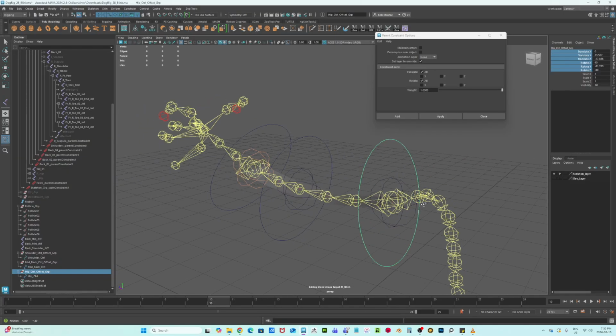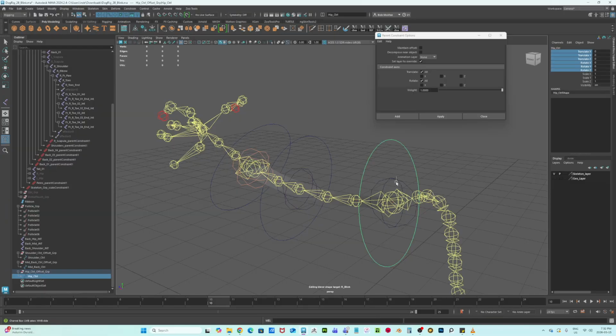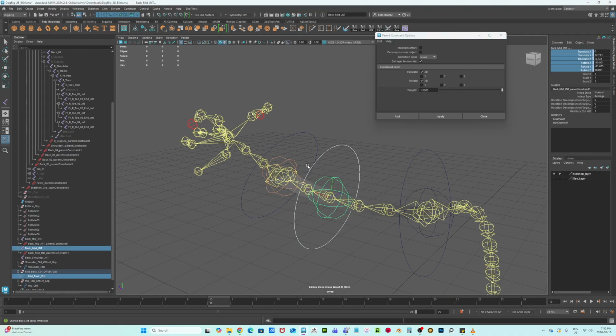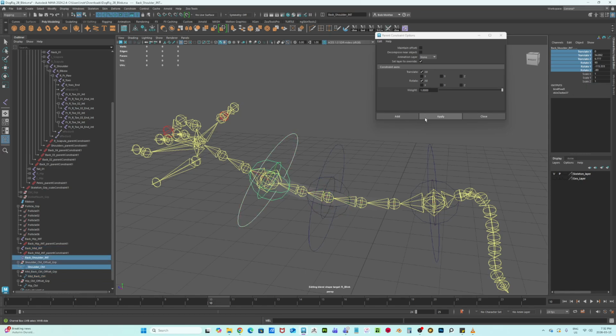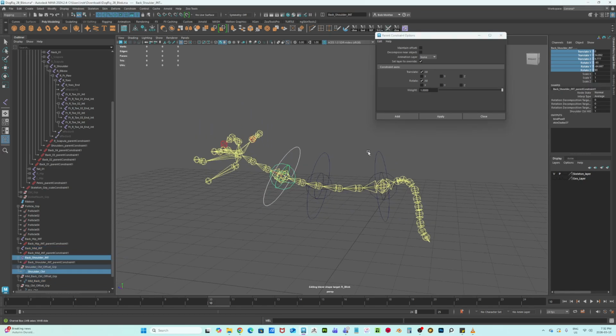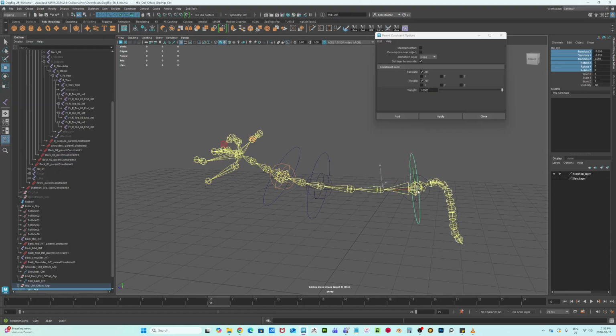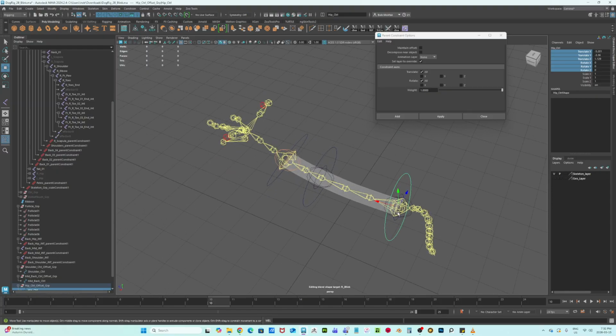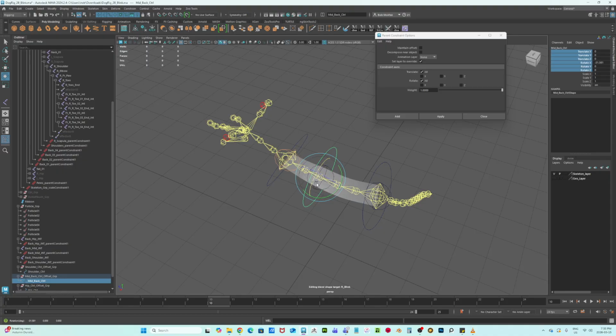And if I grab the controller, grab that joint, and I do a parent constraint, boop, they're done. This joint, done. Curve, joint, done. And if I grab this and I move it, it's going to stretch that ribbon. If I just rotate it, you notice it'll rotate this. I can rotate that, kind of control it.